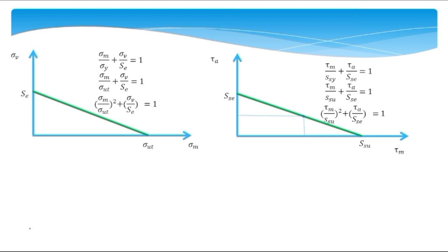Now this is where Zimmerli's data comes in. Zimmerli was a scientist who tested different springs, and he said that material size and tensile strength do not have any effect on the torsion endurance strength when the wire is 3/8 inch in diameter. He tested the springs at a minimum shearing stress of 20 ksi and a maximum shearing stress of 90 ksi, and he said that the springs were safe. This data is for unpeened springs. I will talk about peened and unpeened springs later in this lecture.